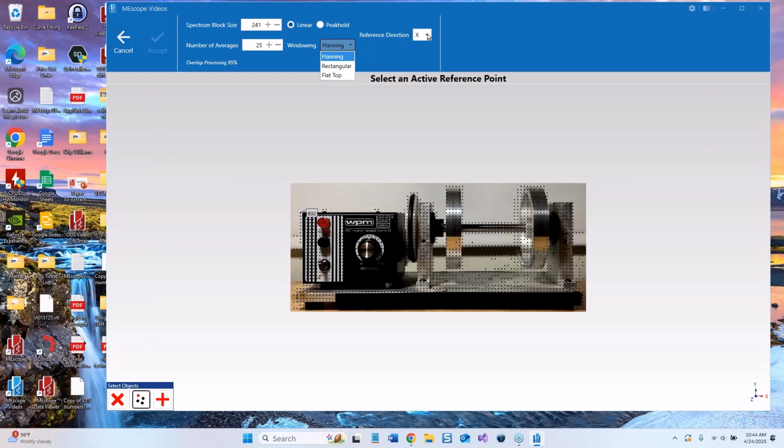And then we need to pick a reference. So this is ODS-FRF. We need to pick a point either in the X or Y, and again, we're going to pick a time waveform as a reference, as opposed to an FRF, where the force is always the reference. Well, it could be the response also. We're getting into signal processing details here.